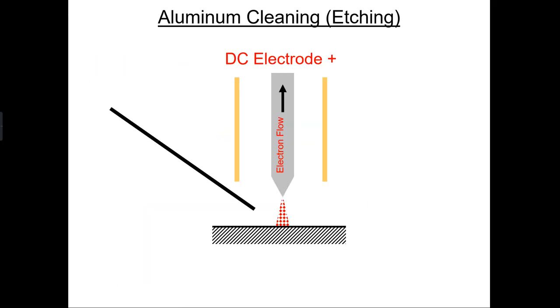So once you start to weld, when we sit on that one side, if the electrode were positive, the arc starts up and it actually starts to strip away layers. That's the best depiction I could give you from a cartoon point of view for what's going to happen. And these areas on the sides are going to be really white. A lot of people believe that has something to do with a deposit or something that's left on the weld. It's actually the bare aluminum being stripped right off.